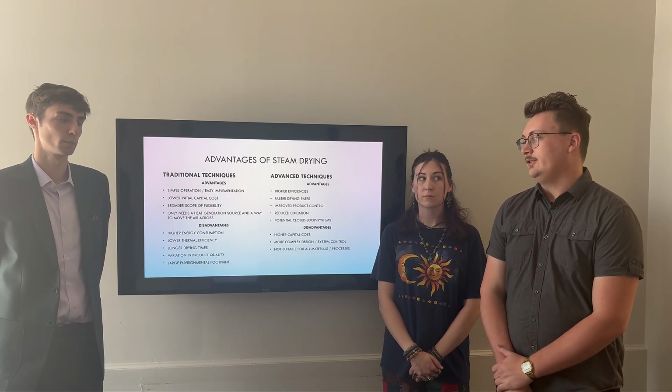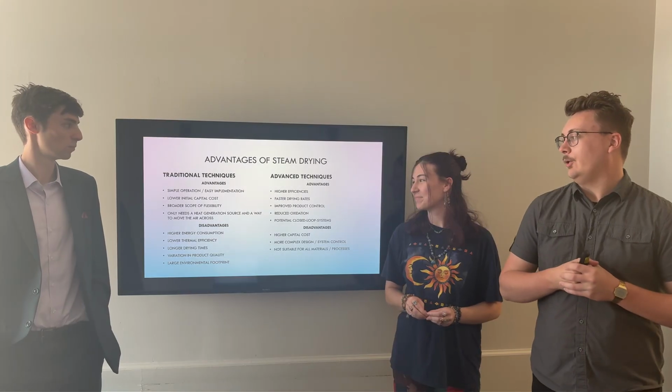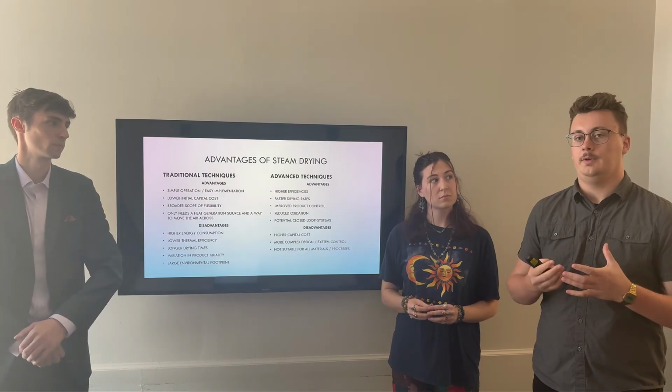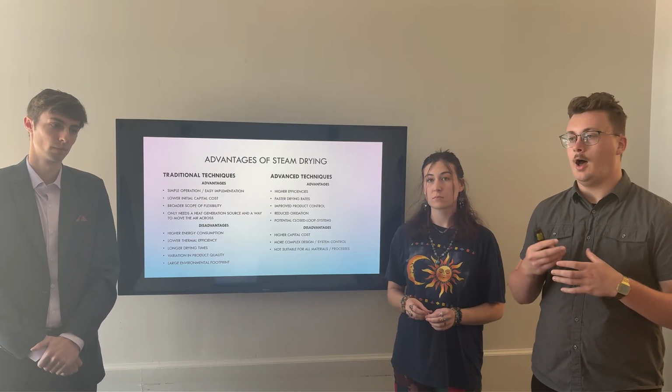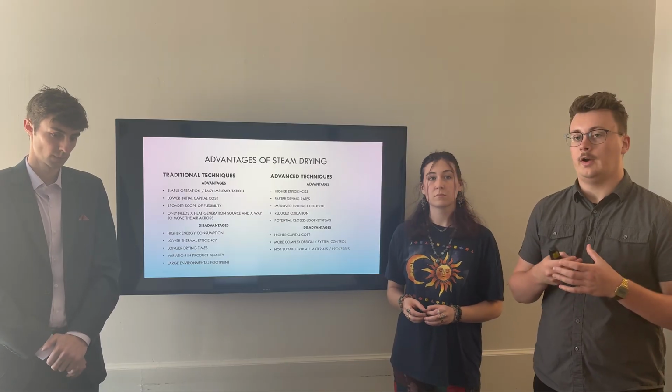But some of the disadvantages to that are it does require a higher energy consumption. It also has a lower thermal efficiency as well as longer drying times. You also get a variation in the product quality due to the hot air being blown onto the product, as well as it has a large environmental footprint.